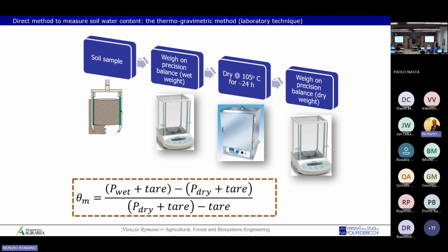Not only binding, because as we will see tomorrow on Friday, there is the cohesion and adhesion of water molecules to the soil particles, and it depends on whether the particles are sandy or clay. But free water means water that mostly can move relatively easily in the soil pores. This is the general agreement for considering free water, and this is important for soil hydrology.